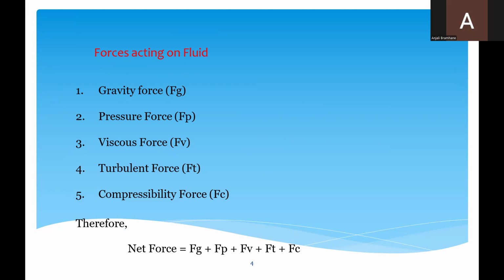There are five forces. First, gravity force. Second, pressure force. Third, viscous force. Fourth, turbulent force. And last one, compressibility force. Therefore, net force equals Fg plus Fp plus Fv plus Ft plus Fc.